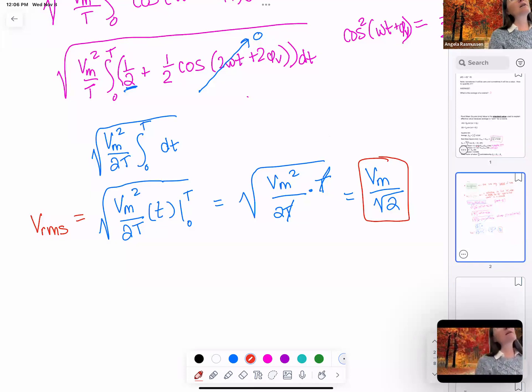This is kind of unrelated, but this really only works over a period, right? Is it the same approach you use if you're not over a period? Good. Yeah, so we use this as the standard way. We assume everything is described as cosines. And so you learn in 1240 that you can rewrite any signal with a whole bunch of sums of cosines. And so you can make an estimate of, okay, I have some chaotic signal and I see the height of that at some point and take this 1 over the square root of 2, 0.707 of that. And that gives you that effective value to use. And so yes, you could use that to create an assumption to work with for any signal at all. Does that help? Okay.